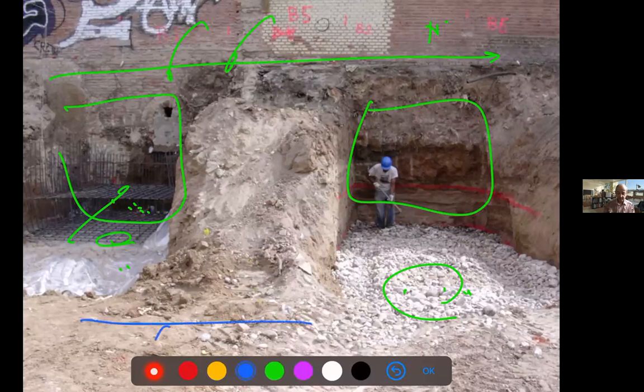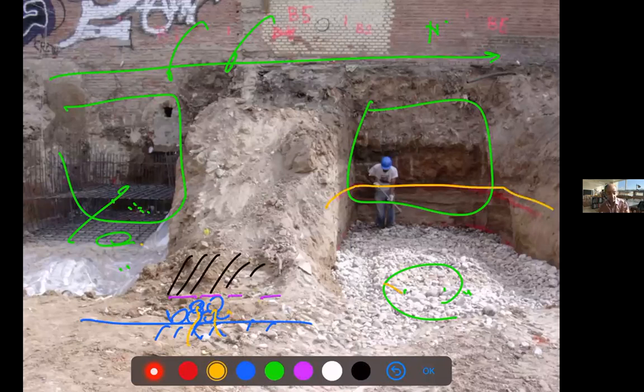So we have the ground. Over the ground, we'll put gravel, right? And then some plastic, and then the concrete will be on top of this, right? So this is what we saw before. This prevents the water to go up, right? It's preparation. You see how we paint the borders. Everything's very rough in the basements.